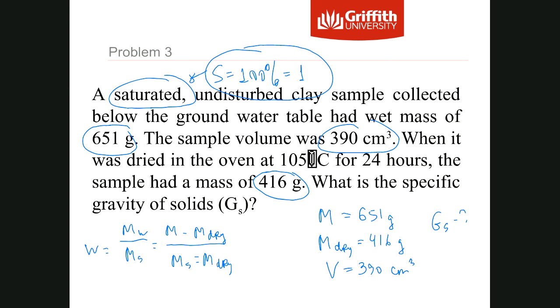So we get 651 minus 416, divided by 416. This gives us 0.565, or if we change to percentage, 56.5% water content, pretty high.